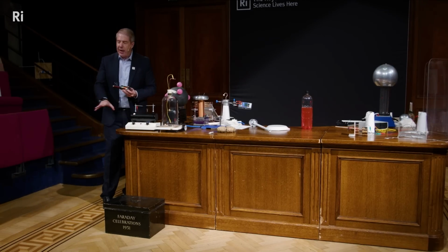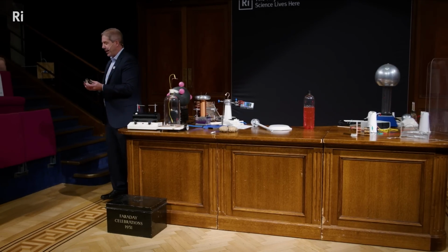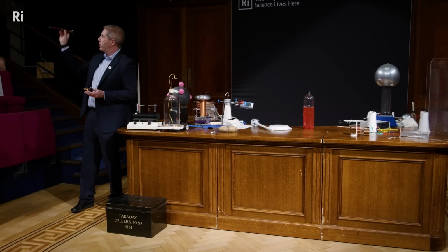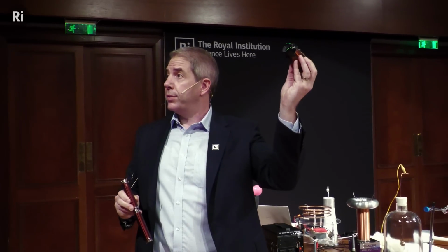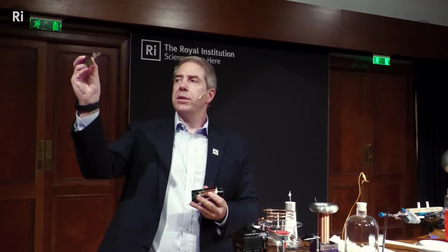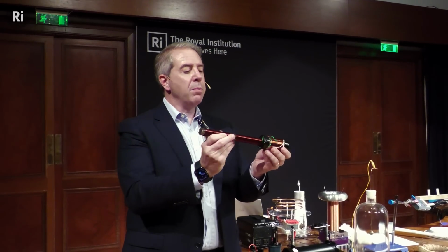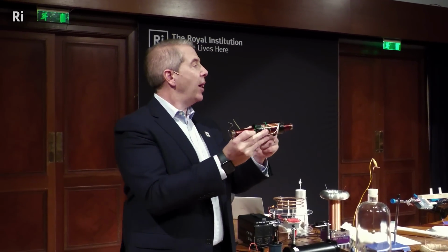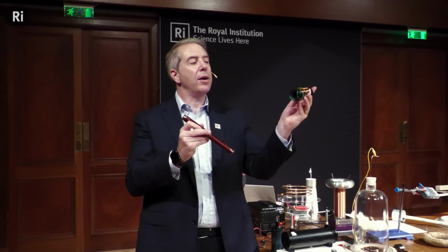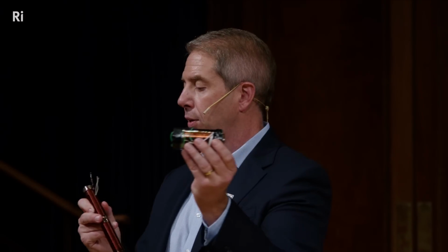And I bought a second one and I took it apart to see how it worked. And so what we have inside is one coil with maybe 200 turns, and then another coil with maybe 2,000 turns. The way this works is we have a change in current in this coil, and it gets multiplied by the difference in coil numbers. So we have sort of a lever to get us higher and higher voltages from this second coil.